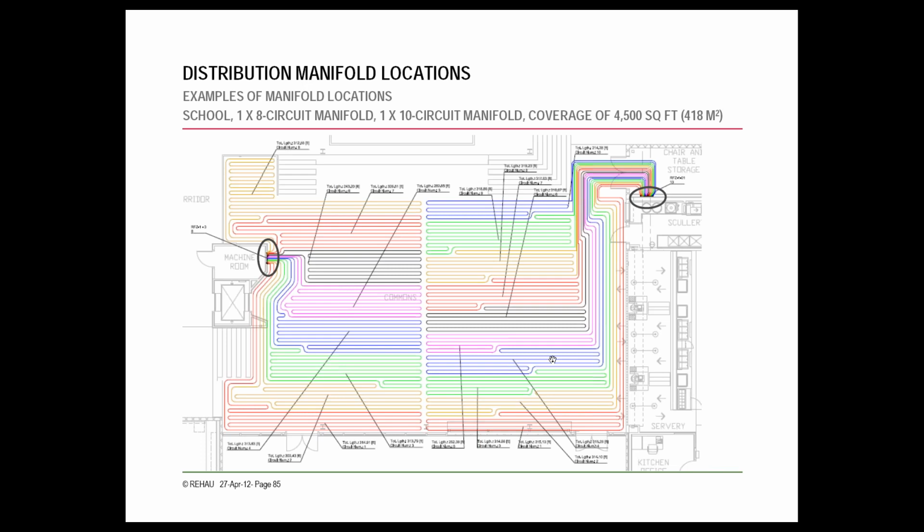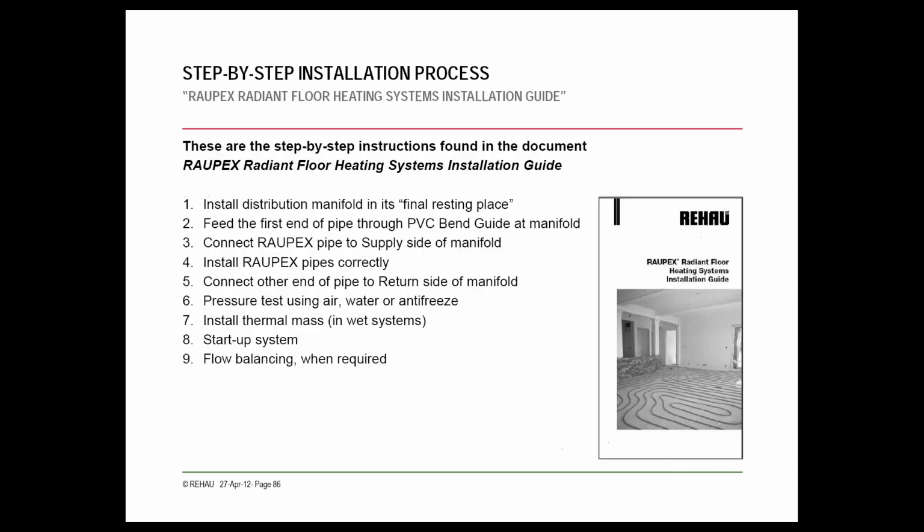To some degree, you're going to have to tell them how much space you need, but they're also going to try and limit how much space you have. So that is another consideration, but as I've mentioned, ideally you want to keep them below like 7 or 8 manifolds. I'm sorry, 7 or 8 circuits per manifold.